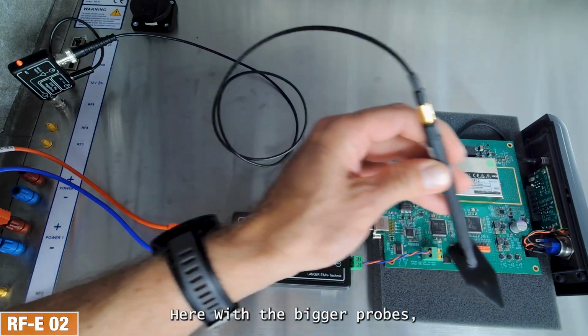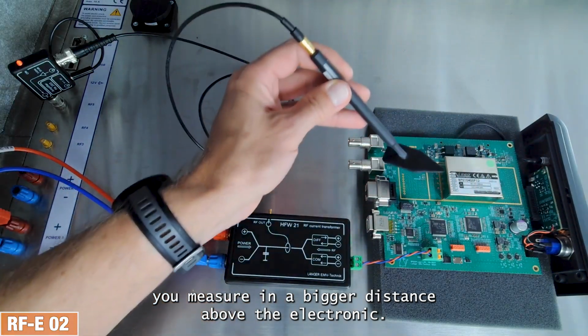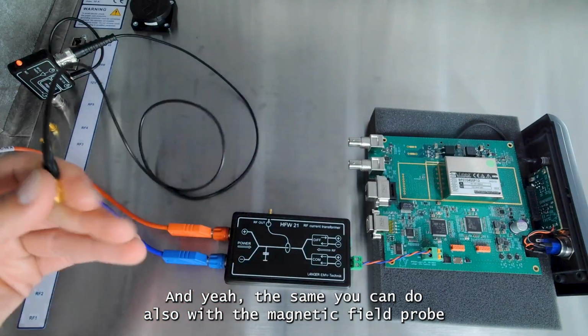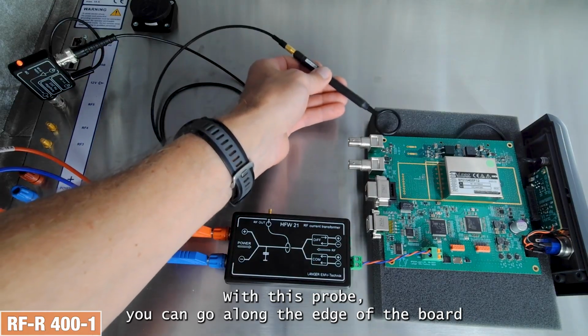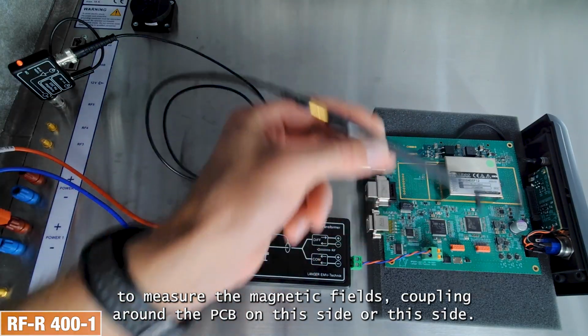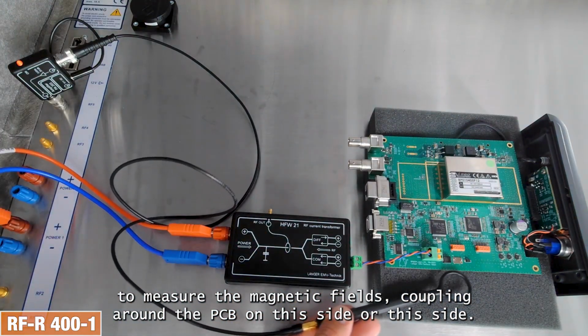Here with these bigger probes, you measure in a bigger distance above the electronic. And the same you can do also with the magnetic field probe. Here I use a bigger magnetic field probe. With this probe you can go along the edge of the board to measure the magnetic fields coupling around the PCB on this side or on this side.